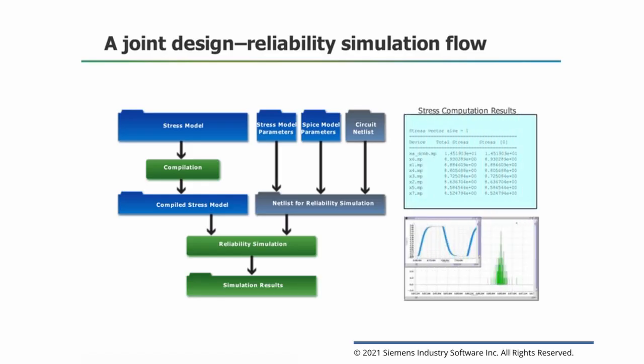To further complicate an already difficult subject, aging appears to be a statistical process itself. If you consider two identical devices drawn side by side, they will have slightly different fresh threshold voltage, drive current and leakage currents. The distribution of these parameters is monitored by foundries, allowing statistical simulations by designers.